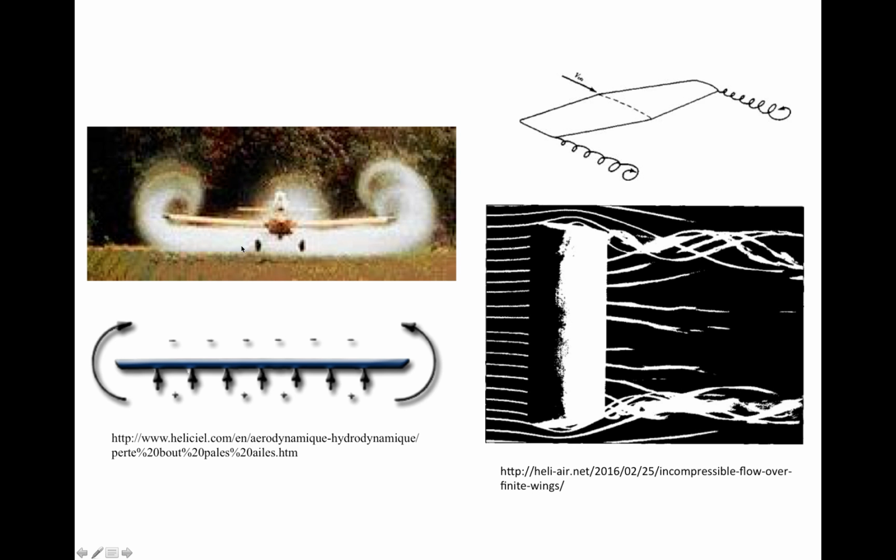If we look at the wings of an airplane, the pressure underneath the wing is higher than that above the wing. This pressure difference caused by the airfoils creates the lift that allows the airplane to overcome gravity. But also because of this pressure difference, at the tip of the wing, air tends to flow around the tip from lower to the upper surface, thereby reducing the lift near the tip. This flow is called tip loss.